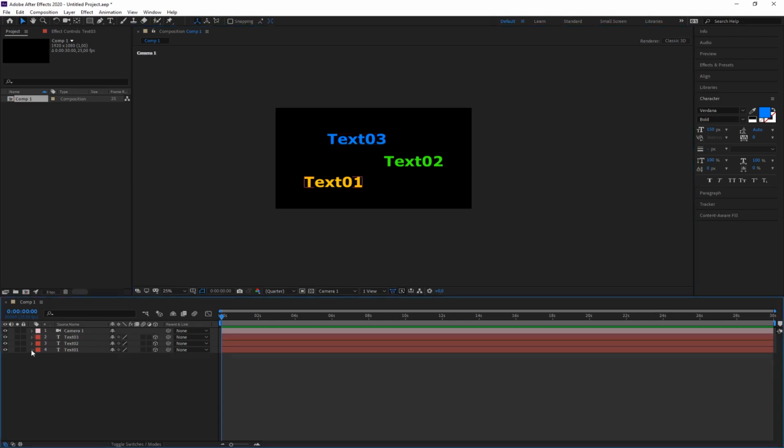1, and I'm going to open the transform, you can see that now every position, scale, and so on, we got some more, now has 3 coordinates. For example, position now has X and Y position, and also Z position. And a Z position of 0 means it is in this plane that we saw when we looked at the scene from the top. Also, rotations are now not only possible in X and Y, but also in Z. And I'll show you what that is.